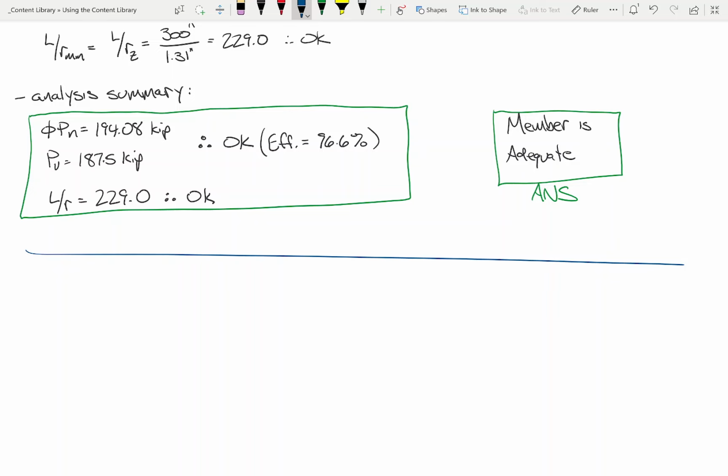I do want to say one thing though about that question. For your homework, really easy. For trusses in general, pretty straightforward. Where your question can get a little tricky is with beams, particularly with shear and moment diagrams. Because you can have dead loads and live loads, and with each one you get a separate moment diagram, and the maximums on those moment diagrams are not at the same spot.